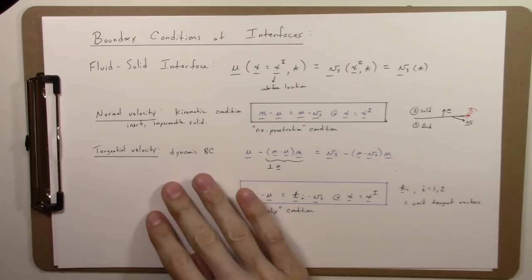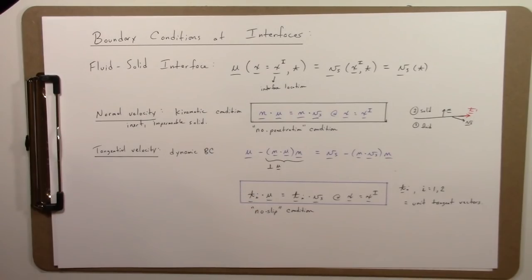So for example, if you have water spilled on this plate and the water is expanding and spreading out over it, the question you ask if the no-slip condition holds, how does the water spread over the solid? And several things can happen. One, the contact angle can be very large and it can essentially roll over, and so it can spread by rolling. Second thing that can happen is intermolecular forces such as van der Waals interactions can pull thin layers of the liquid out in front of the bulk liquid, which can then serve as a lubricating layer to facilitate the motion. You could also have things known as surface diffusion, which will pull out water molecules in front of the bulk liquid and allow it to flow over as well. Or there can simply be slip at this three-phase contact line where the solid, liquid, and fluid all contact each other in order to allow the contact line to move.